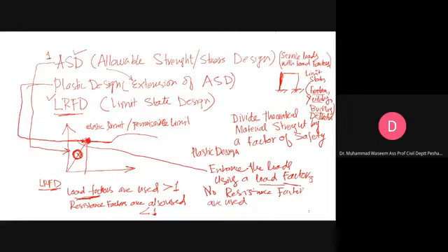Okay, now we know that whenever we design our building, the building lifetime is 50 years, and in the 50 years you have to consider the maximum effect of loads. Like if you are considering the maximum effect of the dead load, it should be coupled with the live load, and it may be coupled with the snow load. Okay, so these loads actually produce some limit states. These are fracture, yielding, buckling. Now in ASD or in the plastic design approach, we do not use any resistance factor.